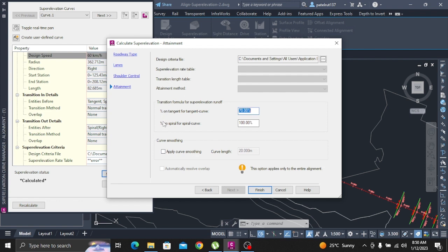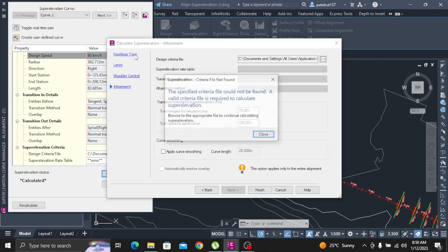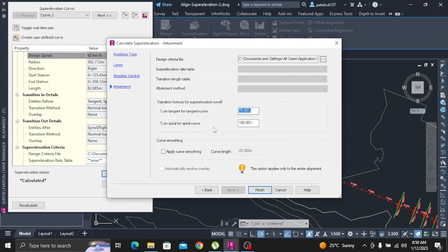In the Superelevation View Style dialog box, on the Display tab, change the Graph Reference Line component type color to white. Click OK. In the Create Superelevation View dialog box, under Specify Superelevation Display Options, in the right outside lane row, double-click the color cell. In the Select Color dialog box, under Color, enter red. Click OK. Repeat steps 7 and 8 to change the other lane colors.